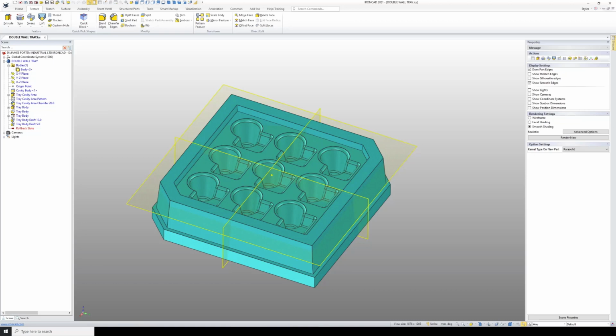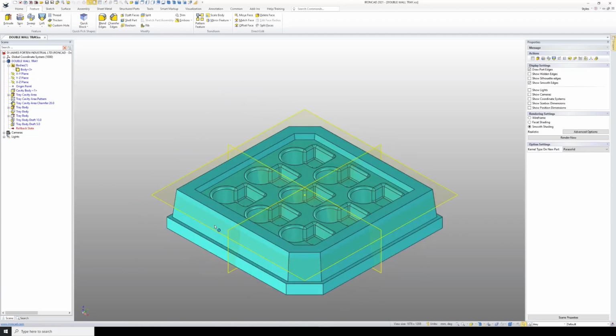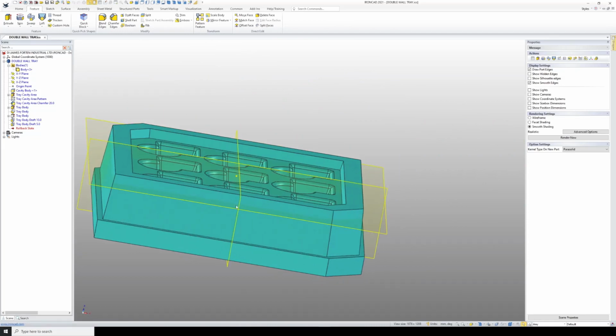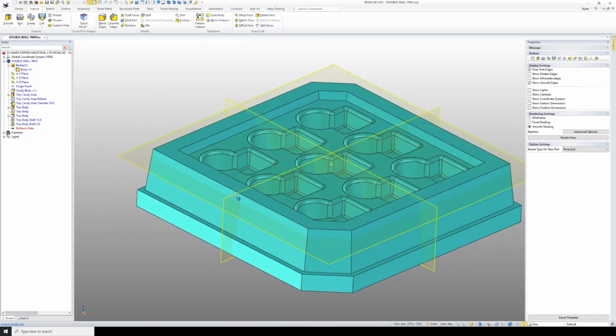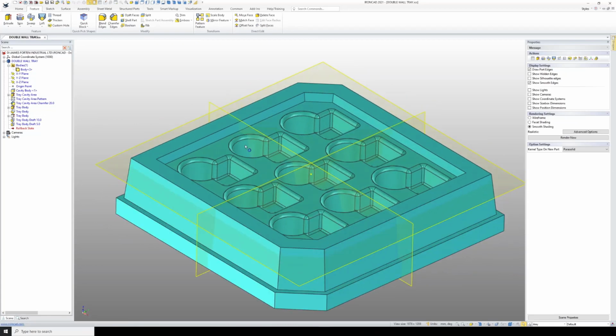And we'll move on, and I'm going to do a reference sketch. So what I want to do is put some cutouts down this side, and the first cutout that I put, I want it always to be in the middle of the tray. So not the middle of this edge, because this edge is offset. So I'm going to create a sketch here that is going to be associated with this top surface, and that I can then lock my cutout to.